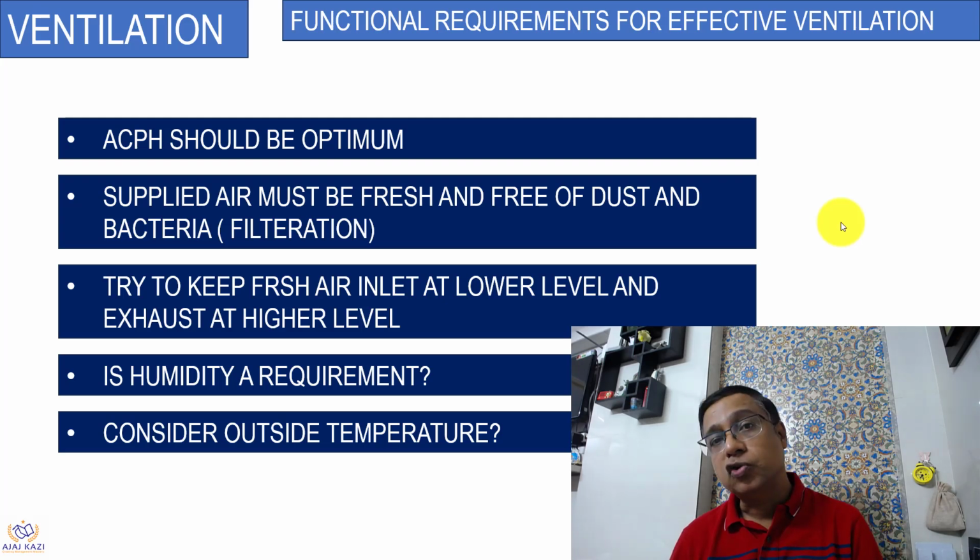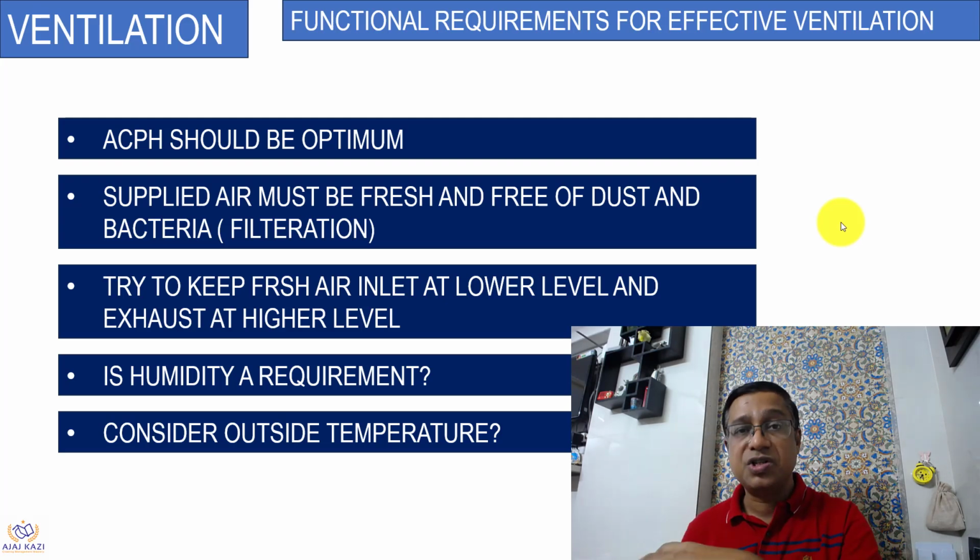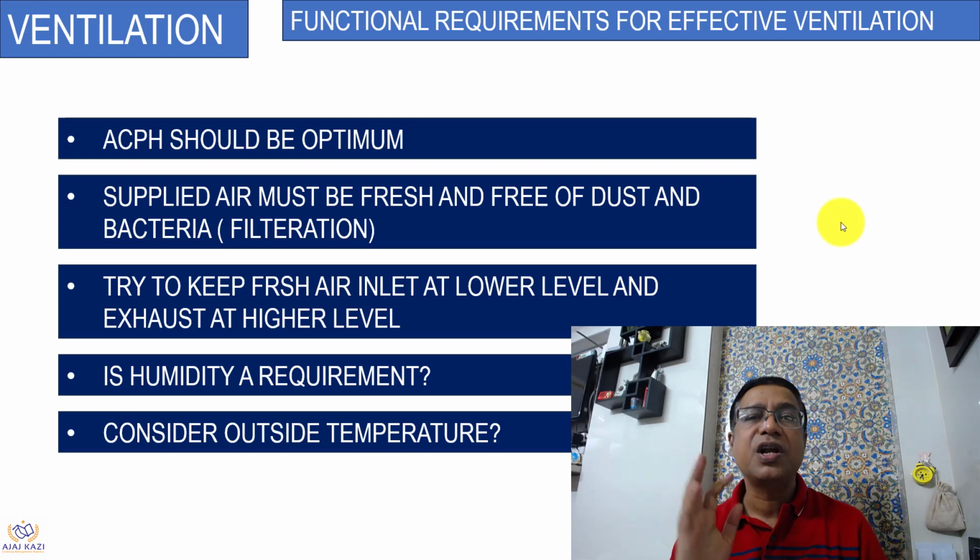Consider also the outside temperature, right? If you have a temperature requirement inside and you want to bring in raw outside air which is already warm, it will not give you the desired result. So you need to be very clear about what the requirements are, right?